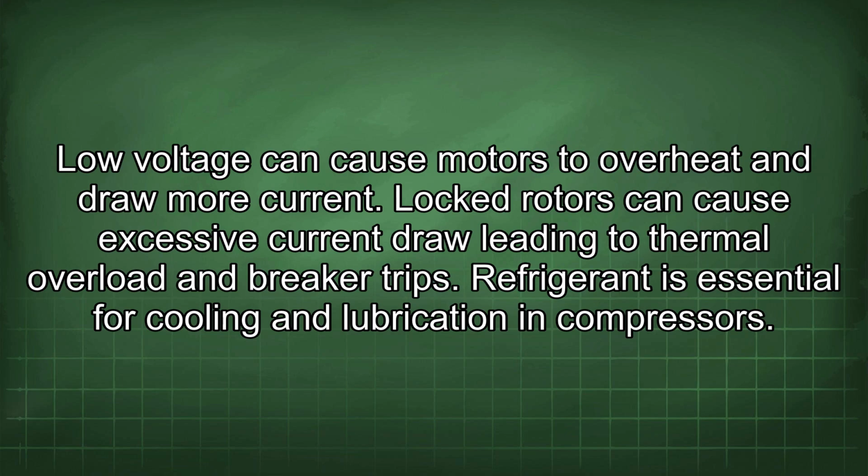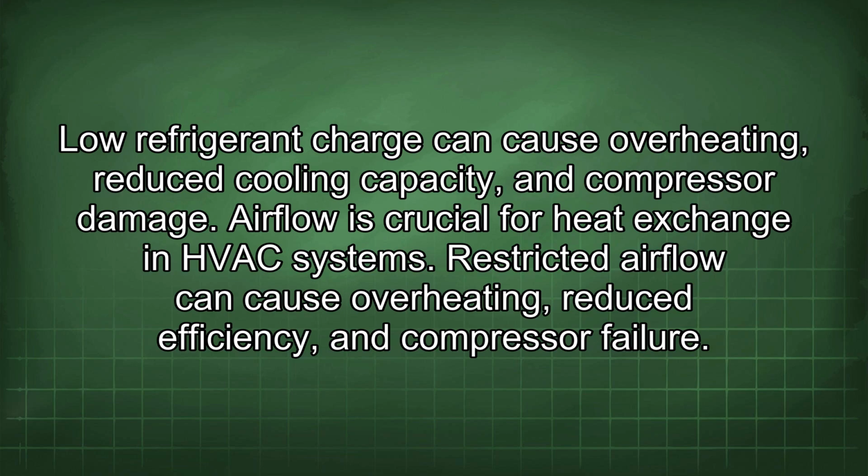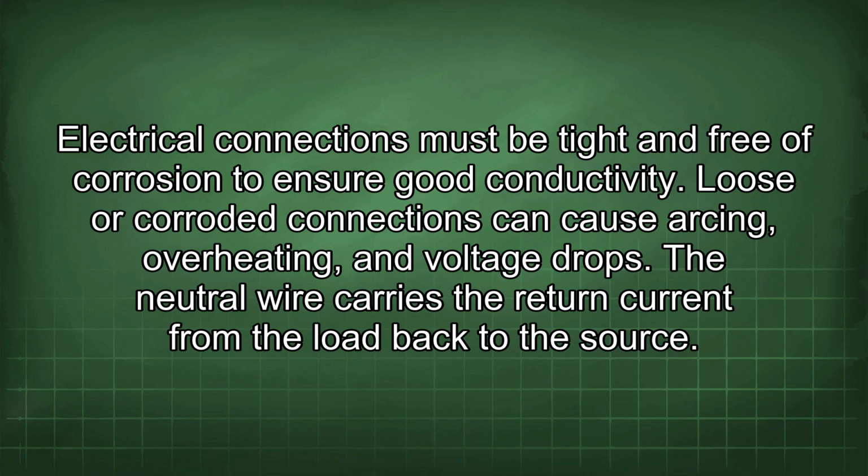Refrigerant is essential for cooling and lubrication in compressors. Low refrigerant charge can cause overheating, reduced cooling capacity, and compressor damage. Airflow is crucial for heat exchange in HVAC systems. Restricted airflow can cause overheating, reduced efficiency, and compressor failure. Electrical connections must be tight and free of corrosion to ensure good conductivity. Loose or corroded connections can cause arcing, overheating, and voltage drops.